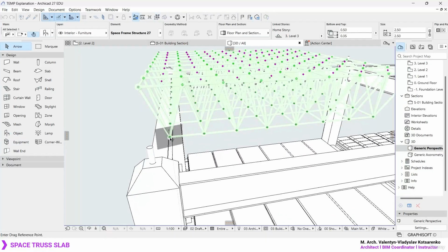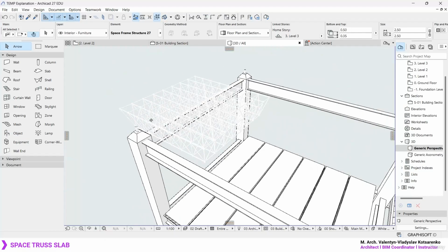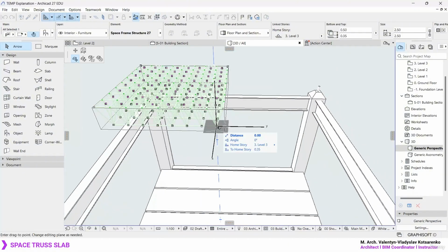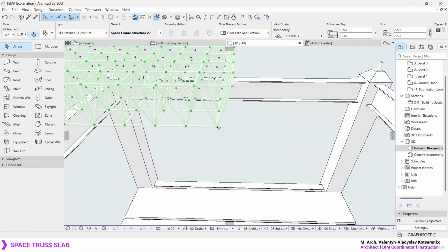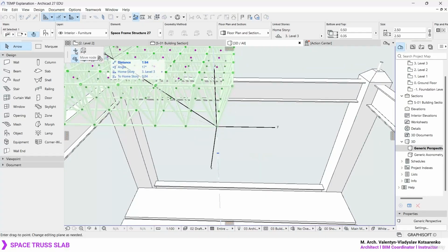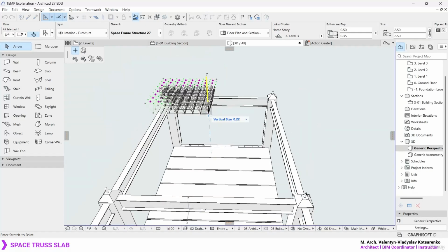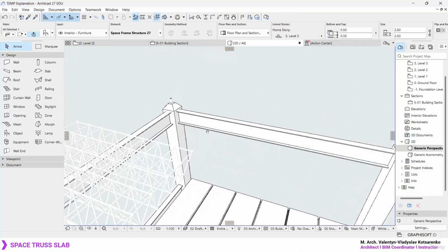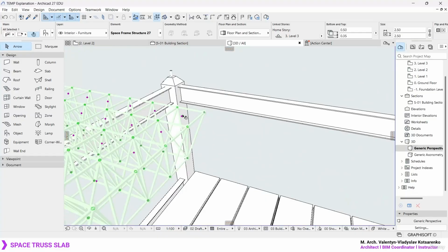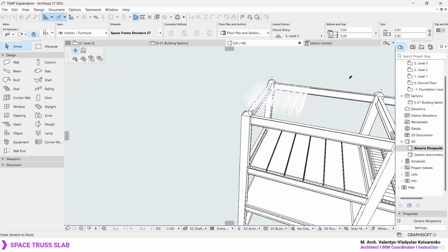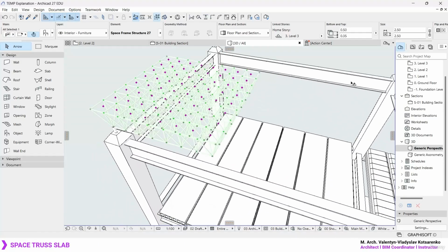And now let's use the 3D view and the 2D view to start adjusting the three-dimensional slab. So you can click on one of the corners right over here and activate the move node command. Now keep in mind that this move node command is a little bit heavy even for my laptop over here. So it's struggling a little bit because it's going to pretty much adjust the structure. This is one of the heavy objects, so be really careful with how you mess around with your object, because it's going to be a little bit heavy for ArchiCAD.